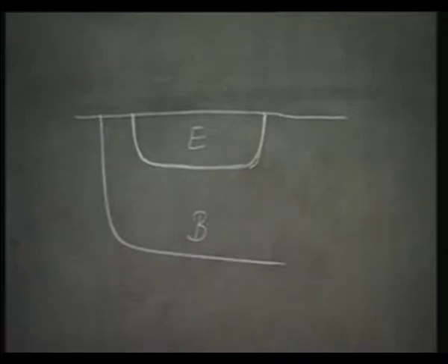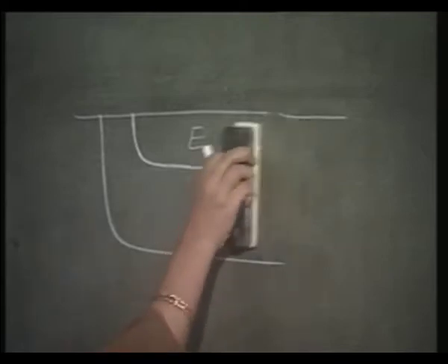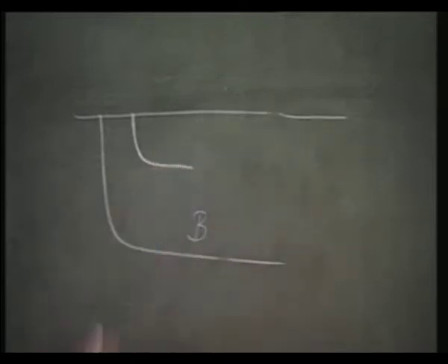And as we reduce the emitter dimensions, you see, increasingly the peripheral capacitance or the side wall capacitance become the dominating factor. As the emitter size reduces, the speed does not really increase to that extent, because now the peripheral capacitance is dominating instead of the planar capacitance, and you have not done anything to the peripheral capacitance.